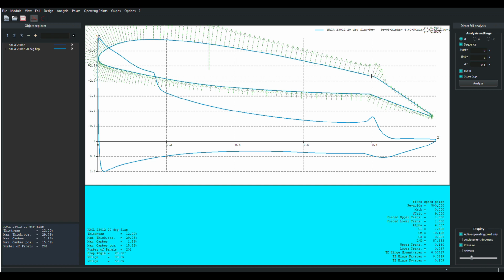And that's why trip strips back here along the hinge line don't work for me. They work on sailplanes, but not for me, because my flow is going just a skosh over 20 miles an hour. And on a sailplane, it's doing 45, 50 miles an hour. Much more energy can go through this barrier. Or you can put little trip strips there, and you have enough energy in the flow that it turbulates it, and then you pick up more energy out of the free stream, and you keep the flow attached on your control surface.